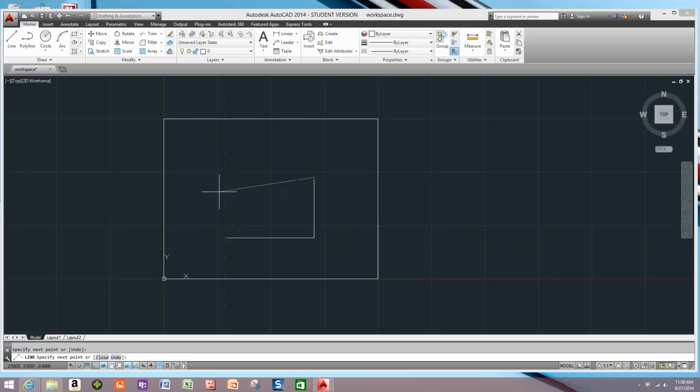Now, let's say that instead of this rectangle, I have a couple of different lines in here. Instead of a grouped rectangle, I have this, where it's four different lines. If I want to, and I only want to delete, let's say, the two outside lines, I can individually just click them and then press delete, and then they will go away. Now let's say that I didn't want to do that, so I'm going to press U, enter, and it'll undo my last step.